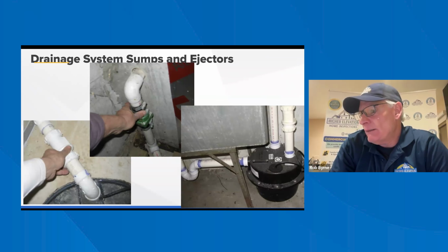Types of pipes. Waste pipes carry liquid waste without fecal matter. Soil pipes carry waste containing fecal matter. That would be going through your sewer. And the stack is the main vertical drain line serving multiple fixtures. Stack vent extends above the highest fixture and acts as a main vent, while a vent stack provides additional air circulation to the system.